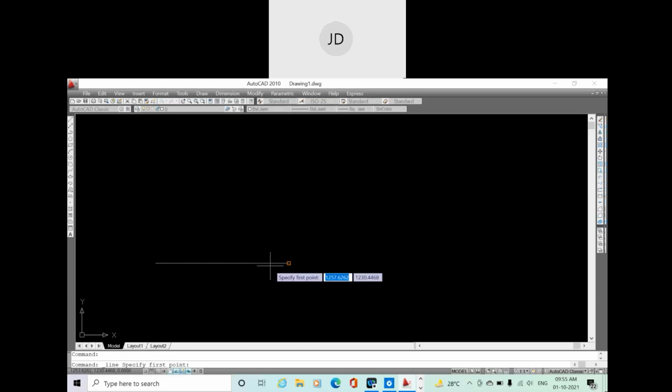This is the first line, and the end point is denoted by the square symbol here, and we have to click here and consider this as the first point of the second line. So I'm clicking here. Now see, the line is created. Next, we have to give the length of the line and the angle. Again the same way, we give the length of the line, suppose 100 again. Next click on the tab button from your keyboard, and next angle. Now see, what should be the angle of this line from the horizontal? It should be 90 degrees, isn't it?